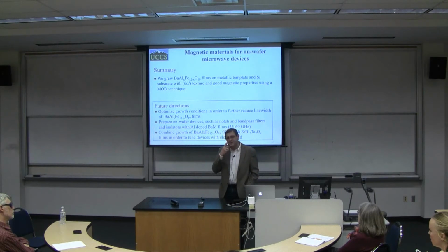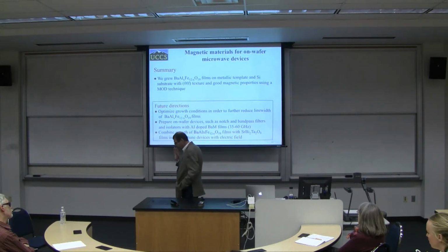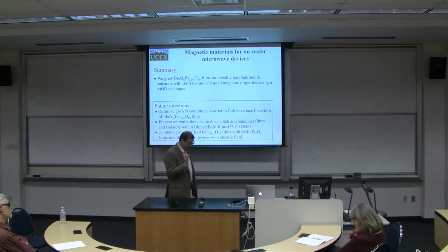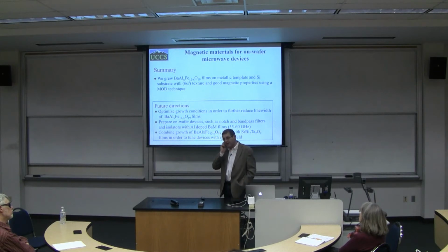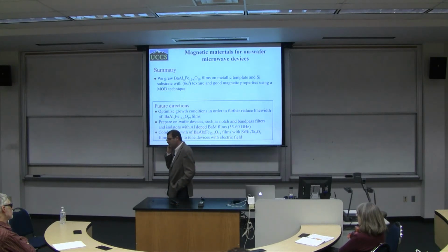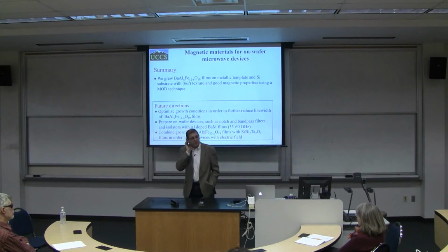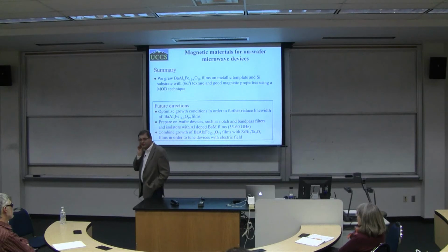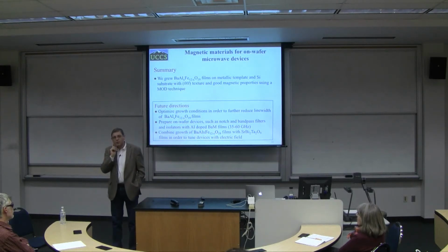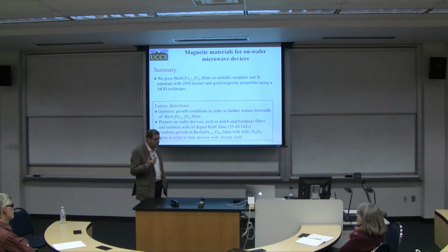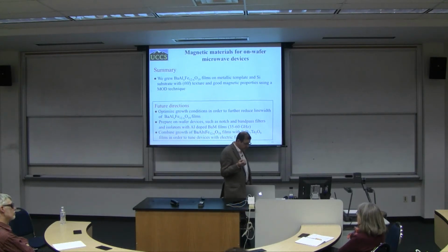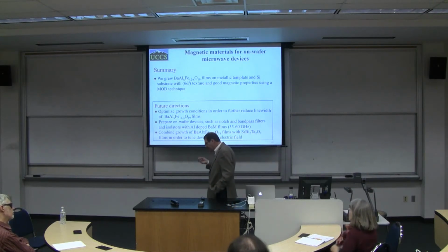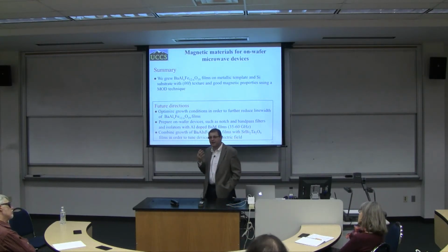We tried different materials. For example, we tried a combination of moly and platinum, and it didn't work. Basically, the moly was alloying with platinum and causing the problem. Platinum has one big disadvantage, which is that it is not very conductive. It's not copper, and we wish to have higher conductivity, because this immediately determines what kind of skin depth you have in your devices.